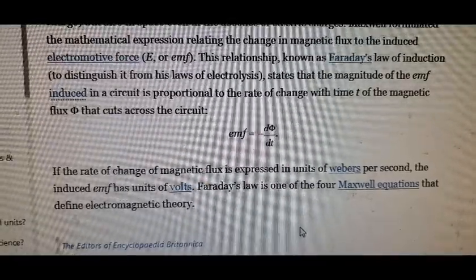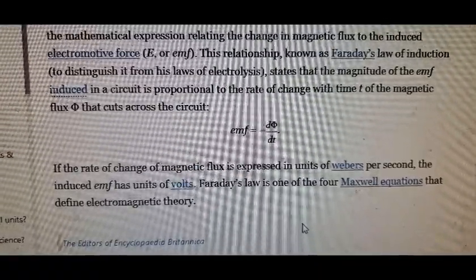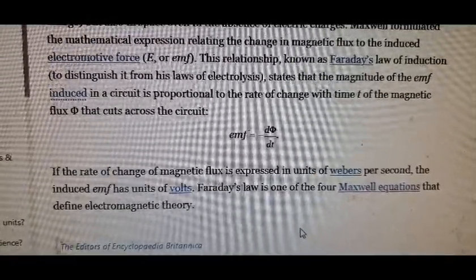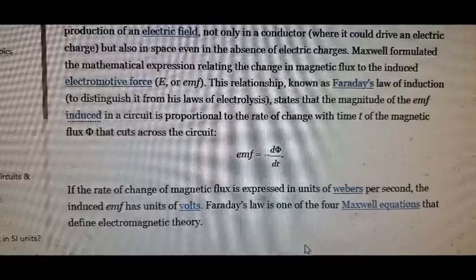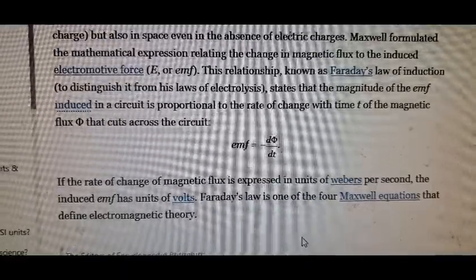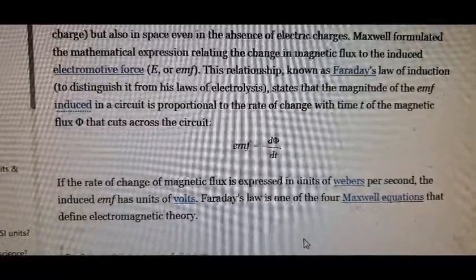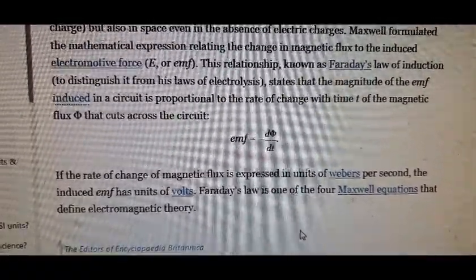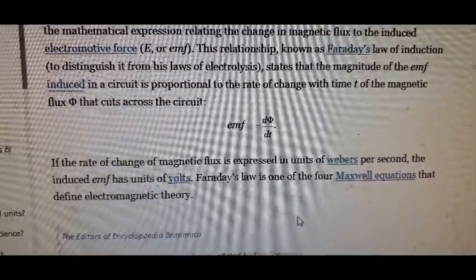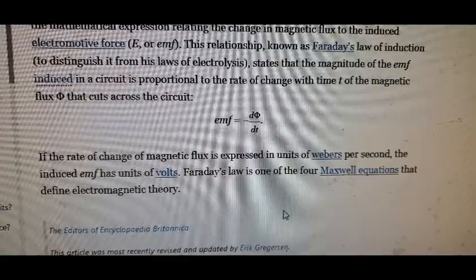So in other words, you could put in energy, current and voltage, to establish a magnetic field of an arbitrary value that might collapse slowly or it might collapse quickly. And the inductive spike will be different depending upon the rate of change of the magnetic field. So that's the first thing, is that the rate of change with time of the field is not directly tied back to the energy used to establish the field, except that you would think, well, that is going to determine how strong the field is.